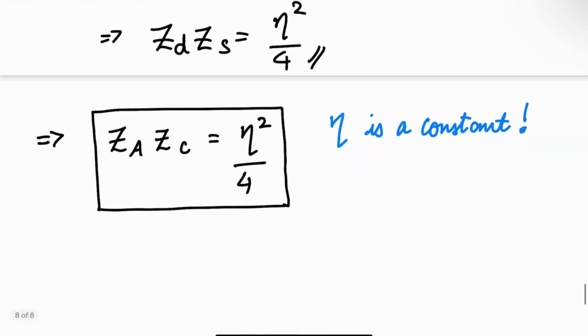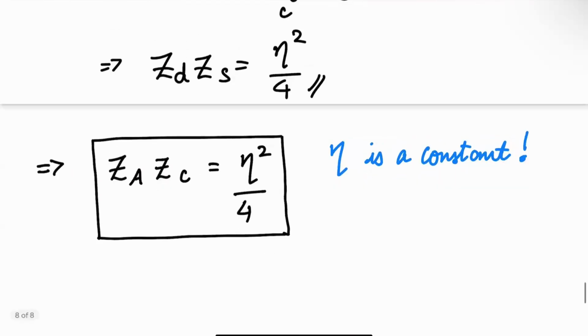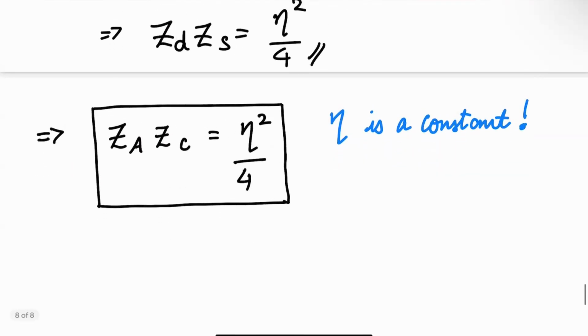Essentially, folded dipole increases the impedance of a dipole antenna by a factor of 4. Because of Babinet's theorem, for a folded slot the impedance should decrease by a factor of 4. Similarly, dipole has an impedance of around 70 ohms, which means that a slot antenna should have 377 squared divided by 4 divided by 73. Whatever that value is, I don't remember, but you can find that.